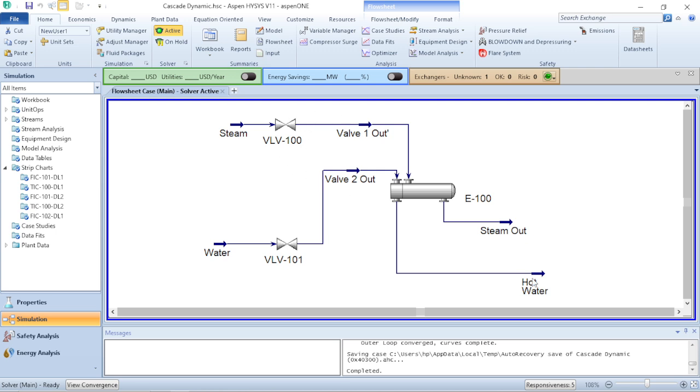So basically what we're going to be looking at in this particular one is making the master set point control the temperature of our hot water, and then making the secondary controller control the flow rate. The idea is this: you make this one the flow rate controller here, and it controls the flow rate of your steam into the system.